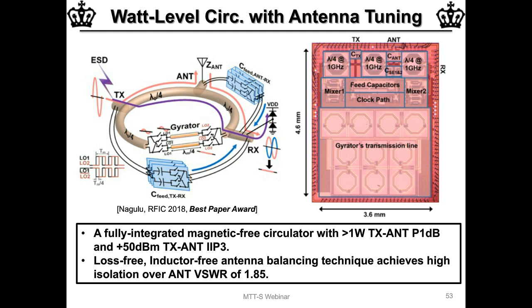Just to give you a sense of what the insight is, it turns out that as long as the phase noise is highly correlated between the switches on the left and the switches on the right, then that phase noise effect cancels and doesn't degrade noise figure. But the moment you have a lot of uncorrelated phase noise between the left side and the right-hand side, then you essentially will have a noise figure degradation. The techniques to mitigate this effect involve trying to keep the clock path as common, and hence as correlated, as possible up to the very end when you drive those switches.